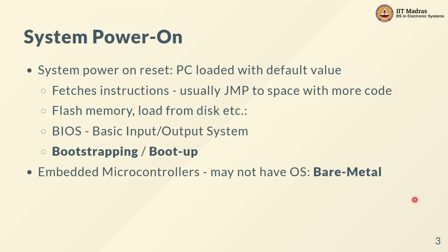You can decide that I'm going to connect up the wires on my chip and on my board in such a way that the default address that comes out is going to get a response, which is going to be valid instructions. Now, typically that's going to be a very small set of instructions because, like I said, you don't have much space to store a whole lot of information. But the good thing about programs is that you always have instructions like jump, which allow you to jump to portions of memory that can have much larger storage, right? So the BIOS might itself be something in the flash memory of the motherboard, which has a very limited amount of information.